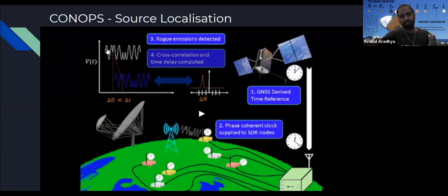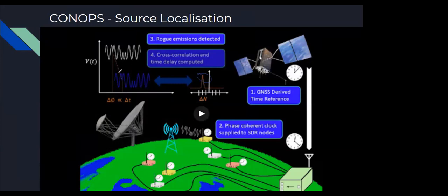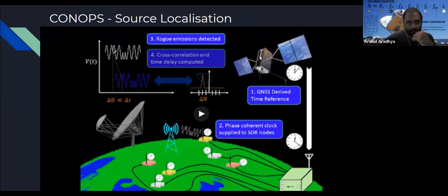So what you see here is this sine wave. This is your signal that's actually modulated by some communication signal. Basically what this correlation is doing, this orange plot here on the second graph, and I'm sorry, I forgot that you couldn't see it, is this: I take corresponding values, I take this value here and this value here at the same location, multiply them, and then sum them all up.